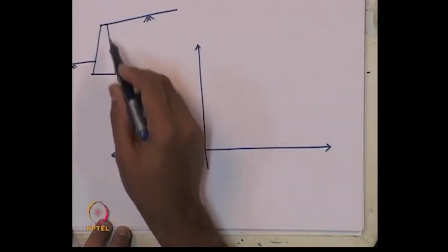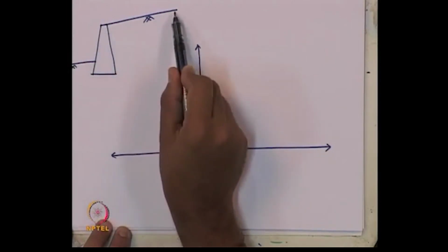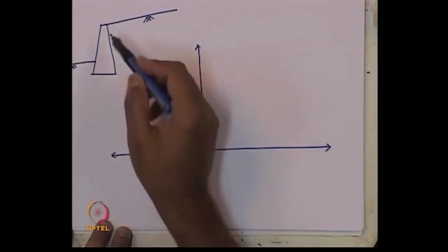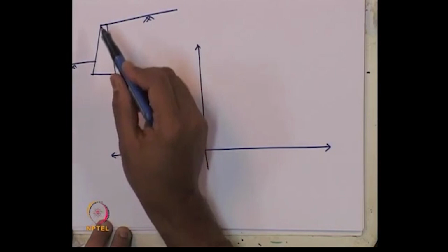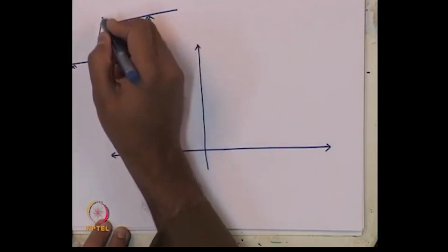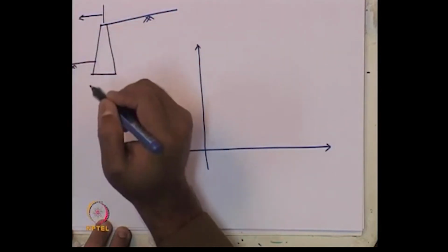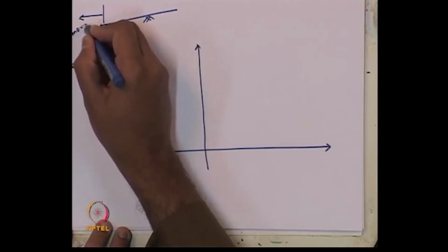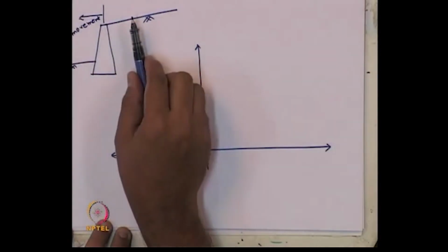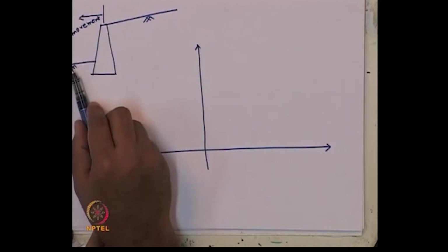So, this rigid retaining wall is retaining backfill soil at this height at one end, and on the other side at this end, this is the dredge level we are calling. Depending on the mode of movement of the wall, suppose this is the main backfill, if the wall displaces in this direction, then we say on this side active earth pressure is going to generate, on this side passive earth pressure is going to generate.